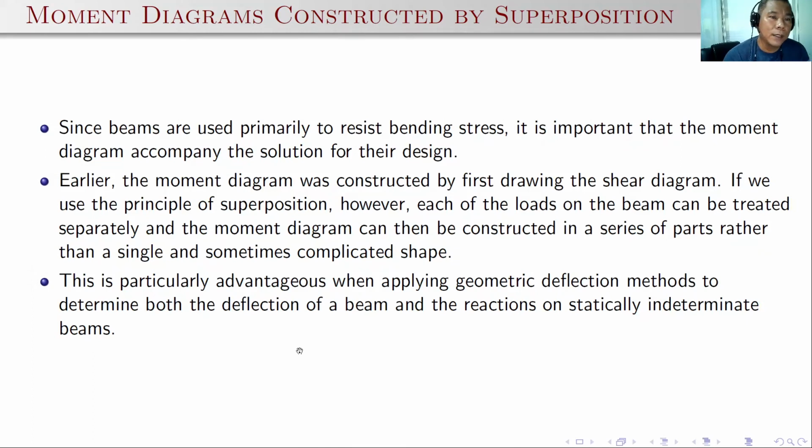Aside from that, moment diagrams can also be constructed by superposition, or we call it the method of superposition. Since after knowing all this, we were able to tabulate actually. We have tabulated a series of beams with different loadings, or we simply simplified it with one type of loading and computed for the corresponding moment.